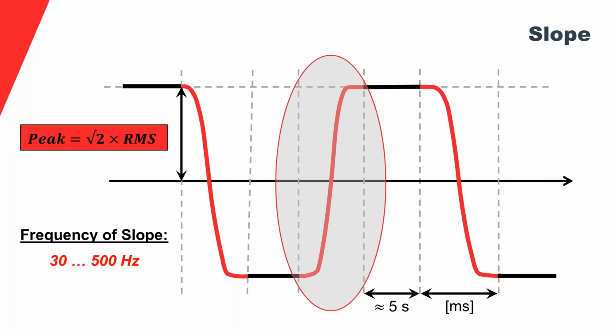So you get the same partial discharge inception voltages, and you get, in principle, the same activity. The difference is typically, because you have this higher voltage stress in the insulation and a continuous wave shape compared to the non-continuous wave shape of damped AC, that the magnitude of the PDs are higher. So if you test a cable, everything in the mapping will be the same between damped AC and cosine rectangular, except that the picocoulomb values will be higher for the cosine rectangular for the slope.